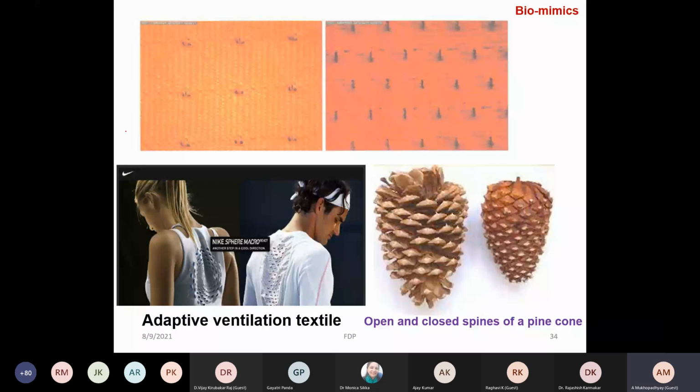So similar in concept here also, like fine foam. Here basically there is a small flap being used. This flap will get opened or closed depending on whether the moist vapor is more or less next to the skin. Because, as I told you already, managing the microclimate is very, very important. Suppose this is the skin side, this is the fabric. So managing this microclimate is very important. This flap will open up whenever there is more and more heat burden or moisture, so that the person can get relief from the heat burden.